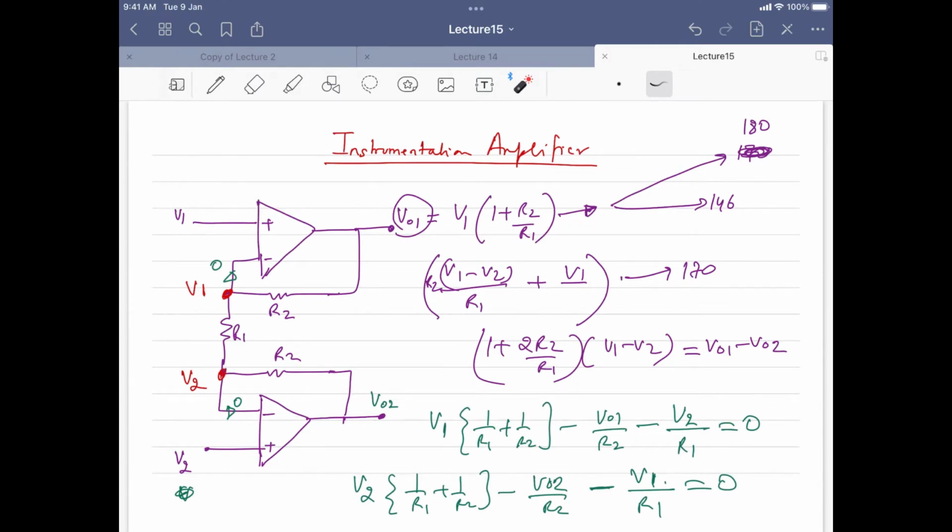See, the thing is, all these things which I was telling you earlier, that R2 is much, much greater than R1 and all these stuff, they were just given to you to provide you with an insight that, if these things happen, then you will get the amplification. But in general, if I am not doing that type of simplification, then you do not have to do all these stuff, because this is something different. It's beyond the expressions. We want to gain some insights from the expression. So in order to gain these insights, we normally do these type of visualizations to actually see whether the amplification is really happening or not, because these things simplify the expression a bit, and then we can find out that amplification is coming when we do these type of approximations. Yes, sir. These are basically some approximations that we normally perform. Okay, so this is actually an instrumentation amplifier.